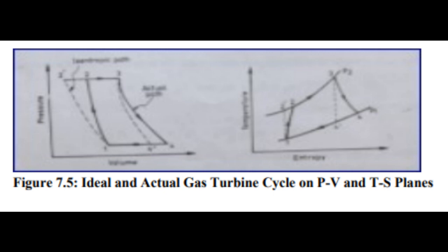In another design, a regenerator is used to transfer the heat to air, the combustion chamber being located at the outlet of the turbine, and the combustion is carried out in the turbine exhaust stream. The advantage is that the turbine handles only clean air.